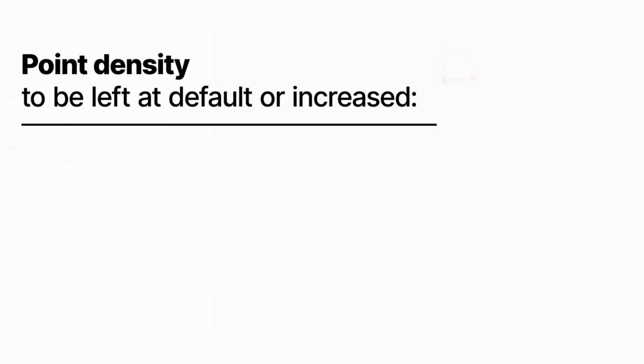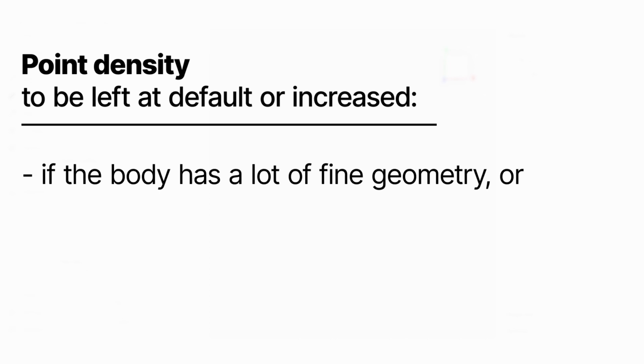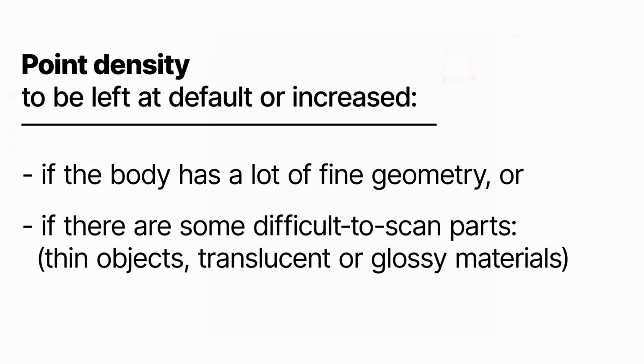Density is recommended to be left at default or increased if the body has a lot of fine geometry that needs to be documented as detailed as possible, or if there are some difficult-to-scan parts, for example thin objects like wires or knives, or translucent or glossy materials.